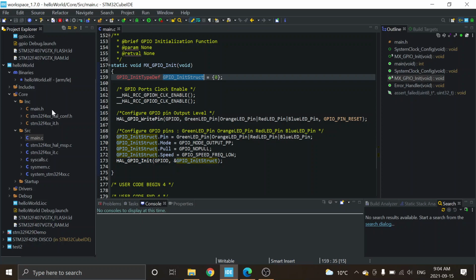One of the things to mention, of course, is that the ARM Cortex system is a 32-bit CPU, and you have been used to 8-bit CPUs with all the PIC. Its native word length is 32 bits; it wants to deal with everything in 32-bit. One of the other things that does for us is we have 32-bit data. We also have 32-bit addressing, which gives us a 4 gig address space. It's not all used, we only have 1 meg of flash, but we have a massive amount of address space that we could put things in. And I'll show you how all of that goes down the road.